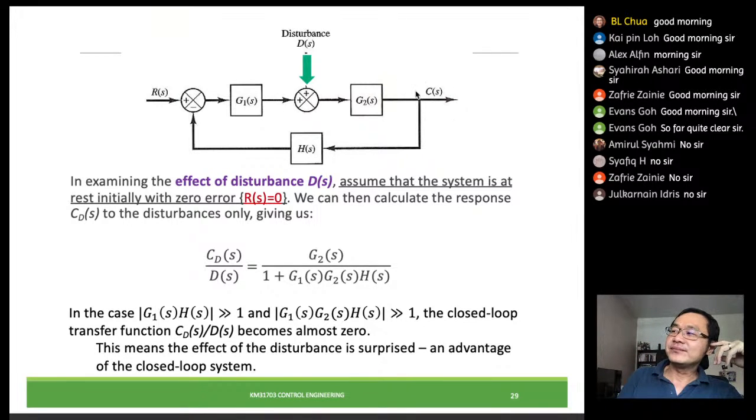combine the output signal due to the disturbance and the input itself. So we try to isolate our problem by putting off this input signal. Let's say now we put the system at rest, meaning to say this input is 0. Then only the disturbance is coming in. Let's say we don't do anything, see what this disturbance will do on our system. So here we will put this R(s) as 0, then we calculate